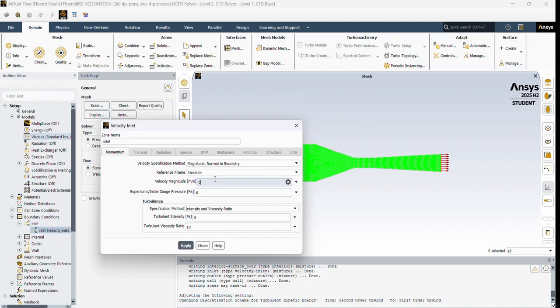So our velocity inlet is equal to the height of the test section, which is 6 inches, times velocity of the test section, which is 4.6062 meters per second, divided by the height of the inlet, which is 22 inches, and that leaves us with 1.2562 meters per second.